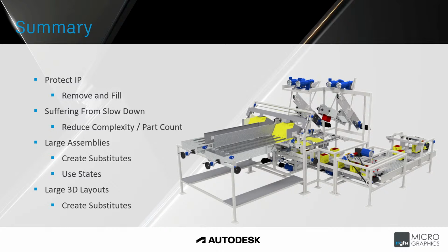We saw for large assemblies, we could create substitutes where those substitutes have been simplified down, as well as the use of states. Within the substitutes, we could have activated a simplified state as well to help with the process. And then when it comes to large 3D layouts, I know that this was just one small machine, but this entire machine could have been substituted out, and we could then do a large factory layout with the substituted assemblies. So that is it for the summary, just a couple of the tools that allowed us to do these things.